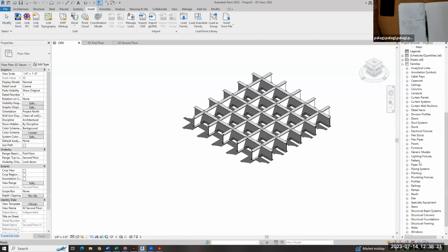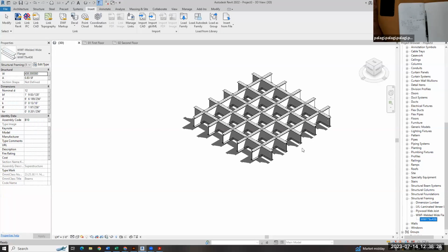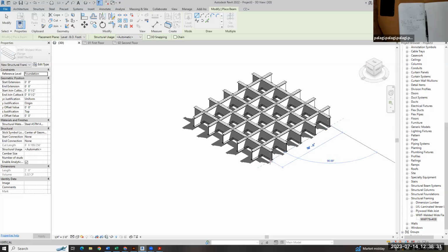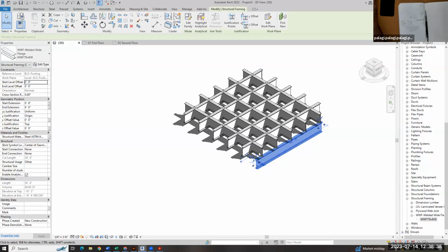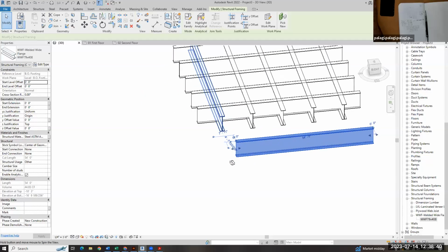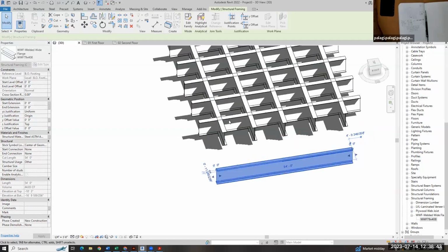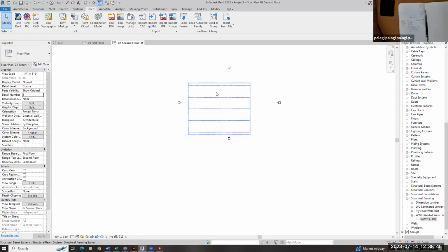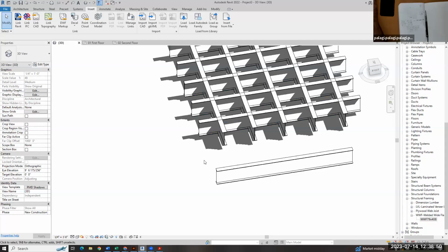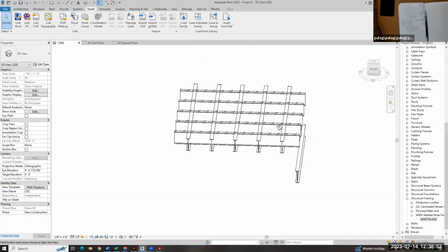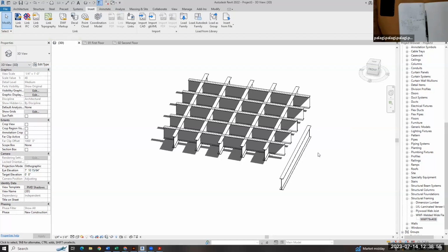Now that the beams are in there, let's say structural, because it's structural framing. There's that view. Grab it. Put the end one on. It went down below, so I have to set it up. The height's the same. So I could set up right there, and align it to get it to line up the way I need. Structural beams don't show in the architecture, so you gotta.